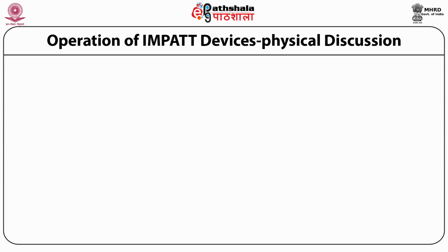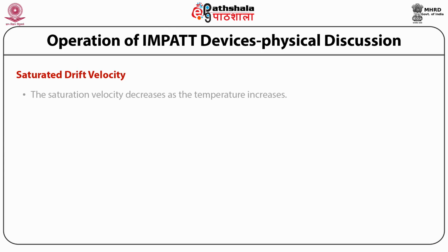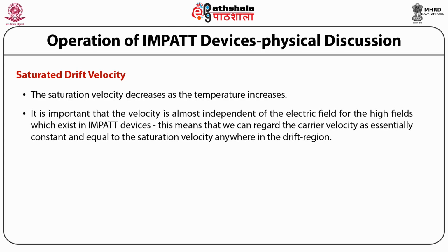Students, let us now discuss another parameter, that is the saturation drift velocity. The saturation velocity decreases as the temperature increases. It is important that the velocity is almost independent of the electric field for the high fields which exist in Impatt devices.